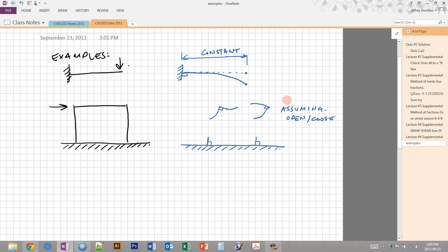And we can see that this drawing, as we've drawn it, doesn't really work. So let's try to draw it again, using the same assumption, and see if we can get the ends to match up. If we wanted all these ends to match up, what would it look like? We know that these beams have to be continuous. There's no hinges. So we have a vertical here, we have our other vertical here, and then let's reduce the twist a little bit. We have something that looks like this, closing, and over here we have something that looks like this, opening.